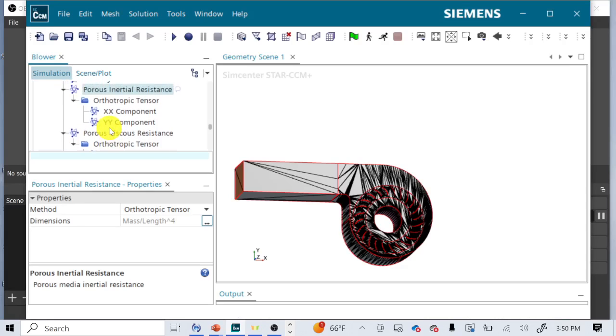So clearly, one case we want to run is going to be no resistance. I equals 0. This is going to be the full open flow rate. This fan is basically running as if you just put it on a table, right? There's nothing getting in its way. It's not trying to drive air through a filter or a sponge or anything else silly like that. It's just completely free flowing. It will move the maximum amount of air possible if I equals 0.